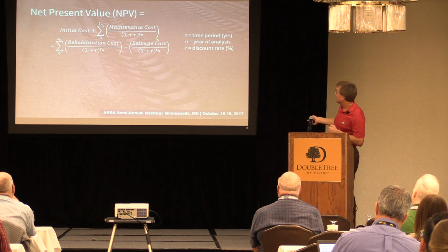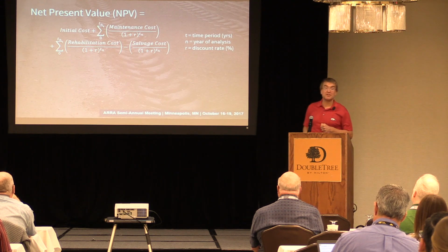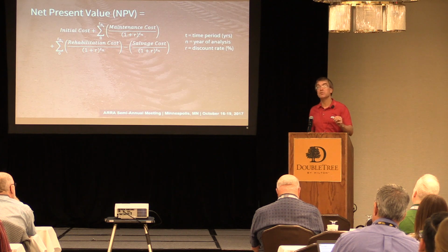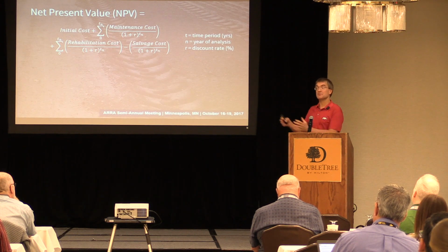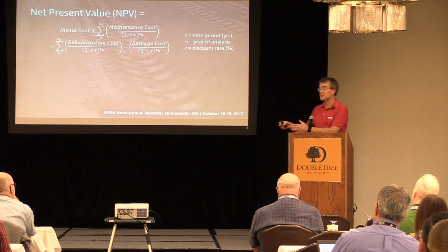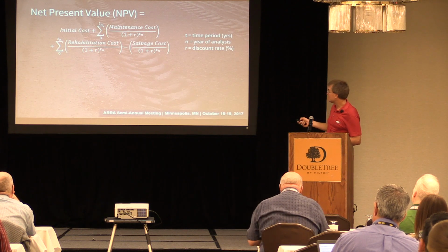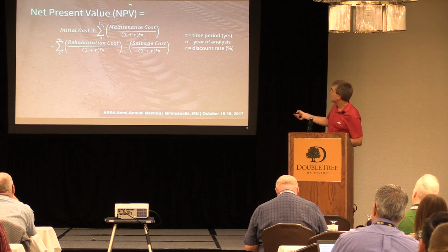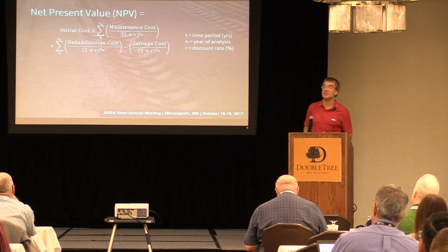And then finally down here at the end, you actually subtract your salvage value. We're lucky to be in an industry where our in-place materials have value. If we mill up our in-place materials, that can be used as RAP materials in future jobs, potentially. So our salvage cost, we actually subtract that because that's some sort of benefit that's coming down the road. And if you take your initial, you add your maintenance, you add your rehabilitation, and you subtract your salvage, you can get a single number. And that single number is your net present value.